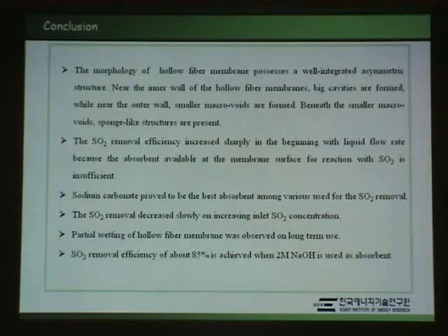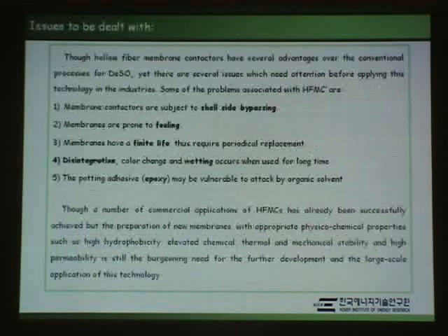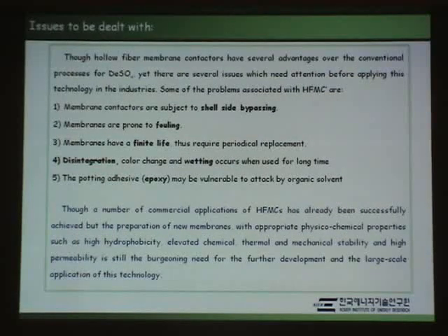We have investigated the effect of several variables, and it was found to be quite a promising technology for removal of this acidic gas. Though this technology, the membrane gas absorption process, is in the preliminary stage, it has several problems which must be dealt with in future, like fouling, wetting, and disintegration. These are some common problems which must be considered, and of course some researchers have proposed some techniques to increase the hydrophobicity and stability of membranes. So these are some issues which must be dealt with in future.